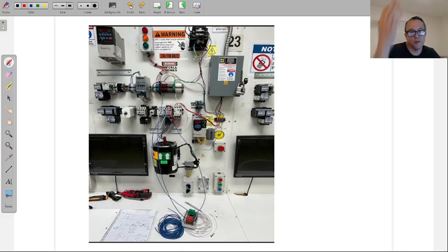So as soon as the amperage starts to climb on that motor, which happens fairly instantly, that overload is going to pop, and then it shuts down the motor, and so it is likely that no other fuses go down at that point. All right, now if a second fuse goes down, then so be it. We'll check the fuses and replace as needed.